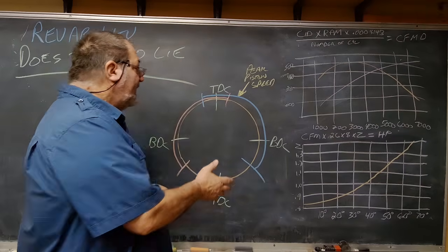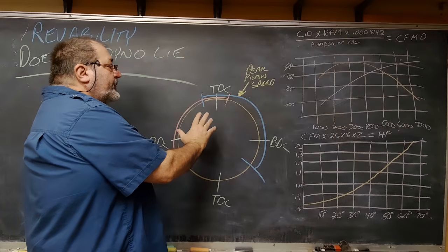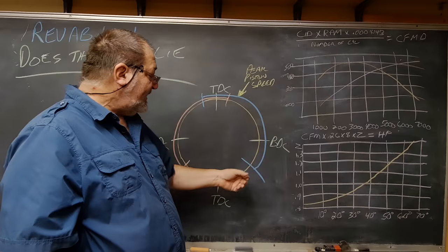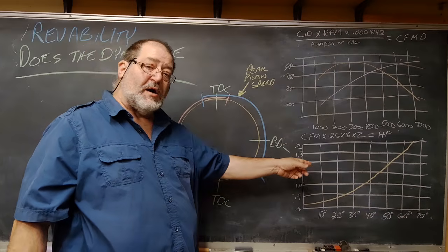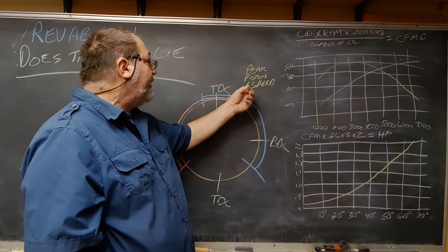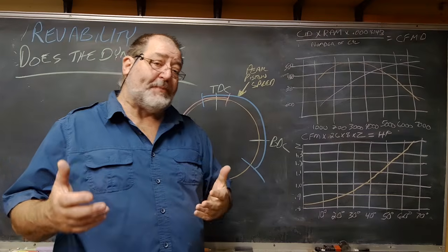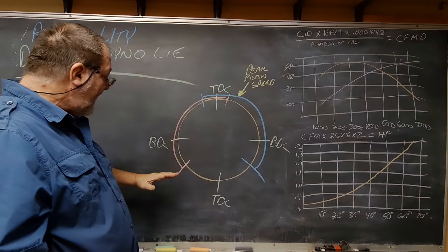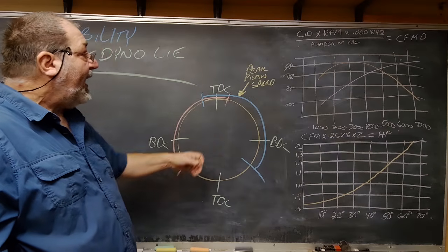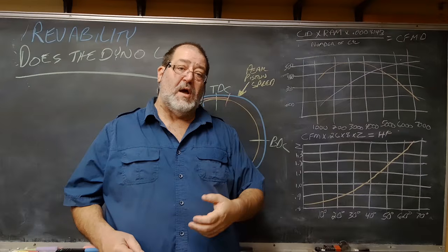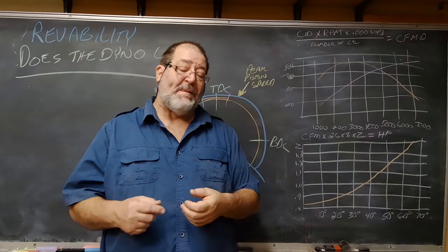I put it in 8 degrees advanced. That's because at the time, I didn't completely understand inertia ramp, but I knew this was important. And that freed up the motor. Between having an earlier exhaust and a better fill at peak piston speed, that engine took off.